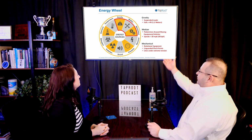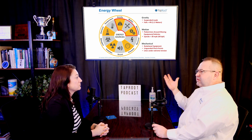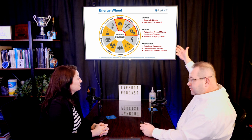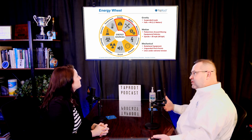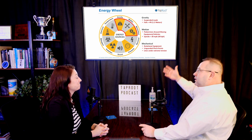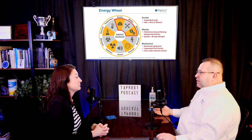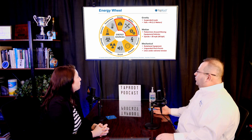Some examples of gravity and motion now. In an industrial setting, we're going to be looking for those lethal type hazards. So here are some examples of those different types of lethal hazards. Gravity: suspended loads, falls above 4 feet. Motion: things that are moving at speeds greater than 30 miles per hour and so on. Mechanical: some of the obvious ones in that picture, the rotating equipment, you pointed out the drill, or unguarded pinch points, but also people overlook things like lines under tension, taut lines. That's an example of a mechanical hazard.